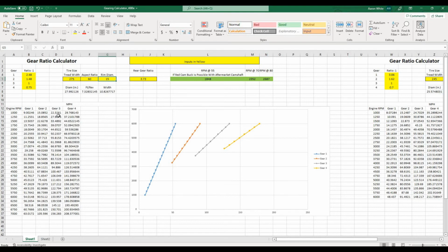Here's where it gets important. Gear 3, that's where we're doing our lockup, right? If you have a 4,000 RPM stall converter, look at the 4,000 RPM column: it's going to be doing 89 miles an hour whenever it's 1-to-1. Whenever your engine speed and your input shaft speed are the same, you're going to be up at a ton of RPM and miles per hour.